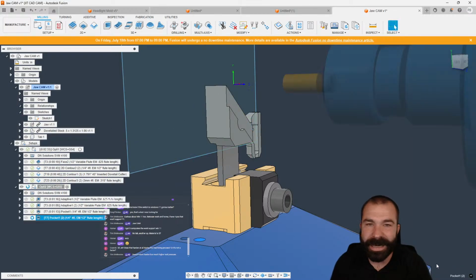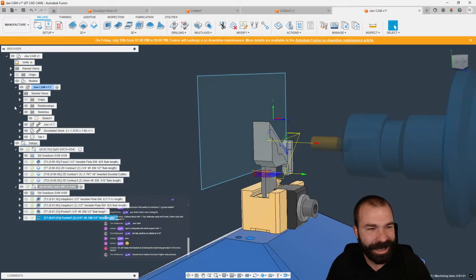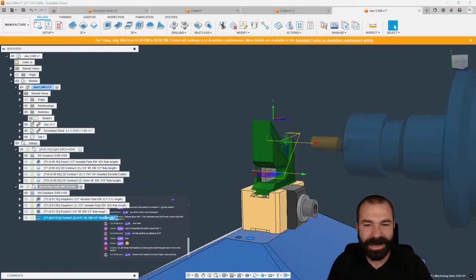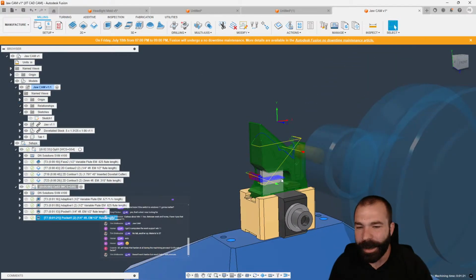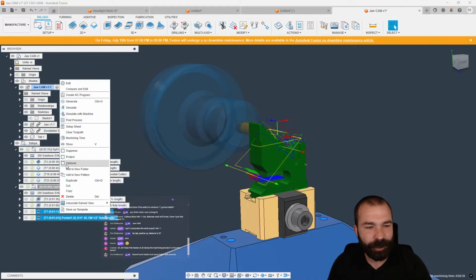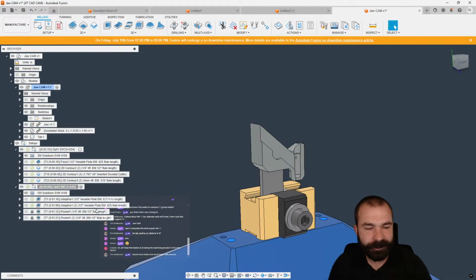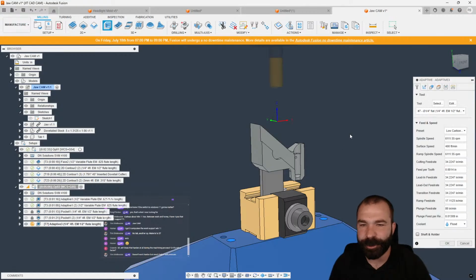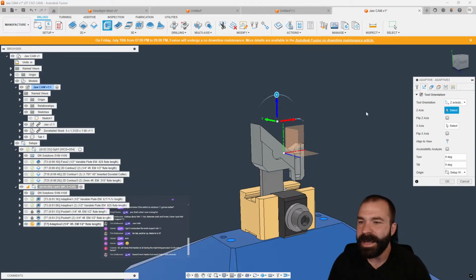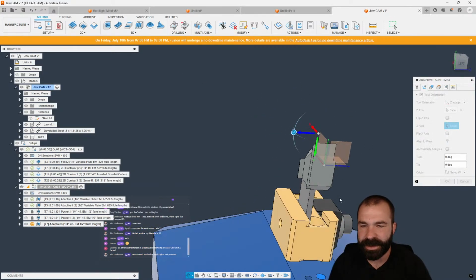And then we're going to protect these so they're locked in, so we can't change them. So again, as you guys can see, we're avoiding going where that rectangle was, right? So if I take these two tool paths and we protect them, now we're going to go in and we're going to recreate what we had going on. So again, this time, little tool orientation this way.